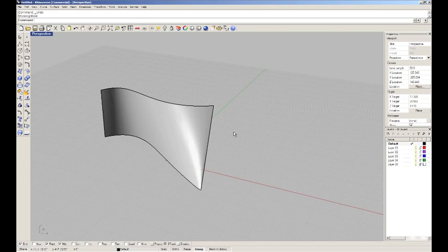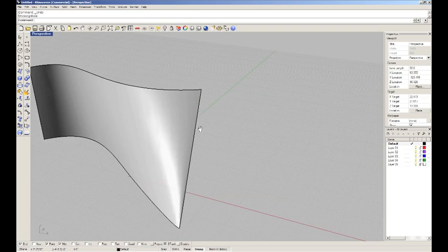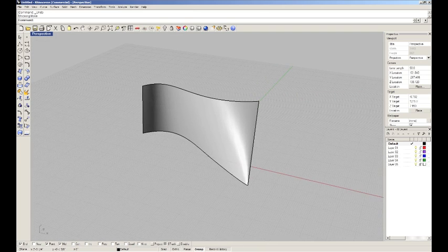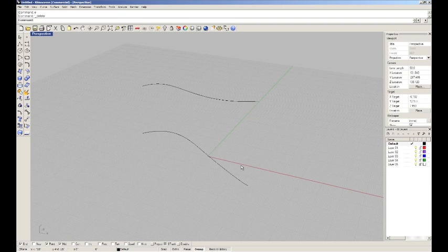Obviously, as architects, it's helpful for us to be able to have these kind of parametric relationships between things. So if we want to define a base structure or base geometry, and then have resulting things that we build up off of it have a relationship back to it and allow for things to constantly update rather than having to constantly be rebuilt. So Rhino started to address this issue by something called implicit history, which is defined down here by the Record History button.